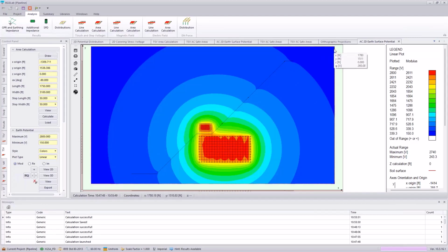At a minimum, or I guess at the maximum distance, it's possible to have a touch voltage when your Earth's surface potential is above that touch voltage criteria. Meaning if you had a pipe that was just coming along the edge of this system and a test lead were right here, or a test valve, it's possible that pipeline may be at 0 volts and the individual's feet will be at 260 volts, and so that could be a touch voltage criteria or a transfer voltage hazard. Now this is going out approximately 1,000 feet from our station.